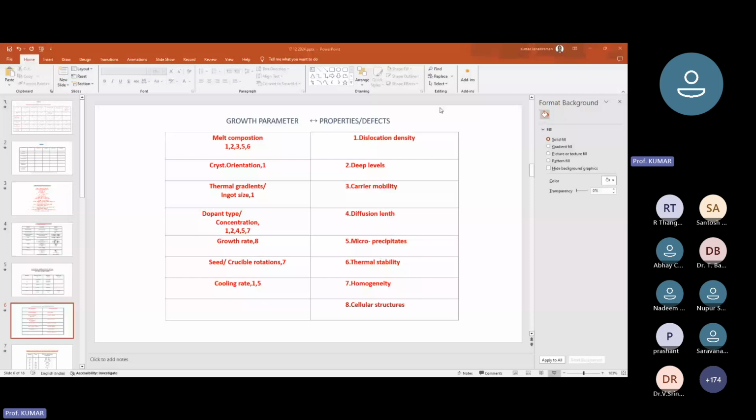So therefore, it will have one excess electron, and therefore it will create what is called an N-type. And the distribution coefficient is in the range of 0.3 to 0.5. What we need is 1. But it's not so easy to achieve 1, but we can get something close to 1. That is how it is being done for most of the selected dopants.